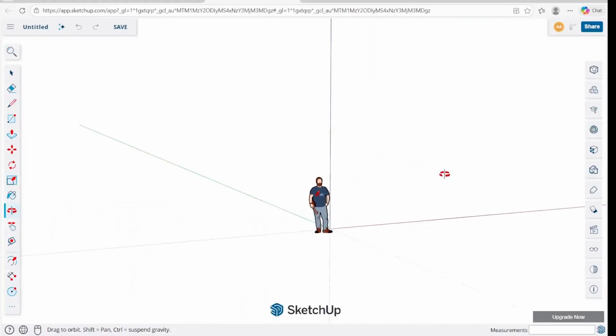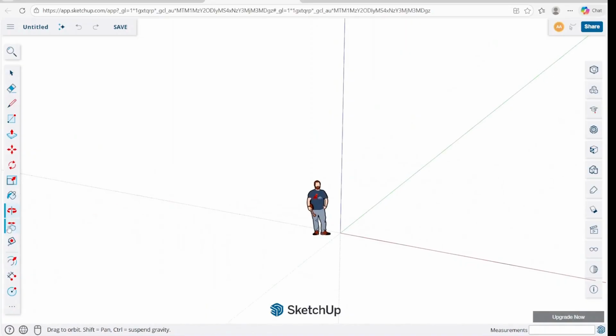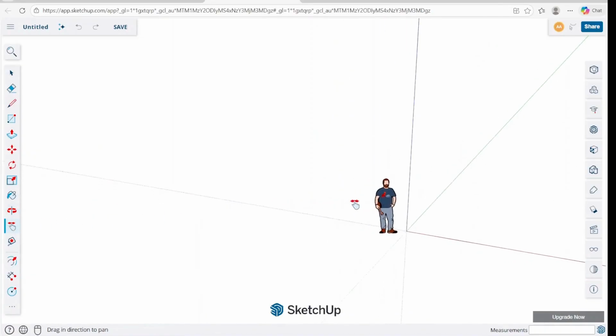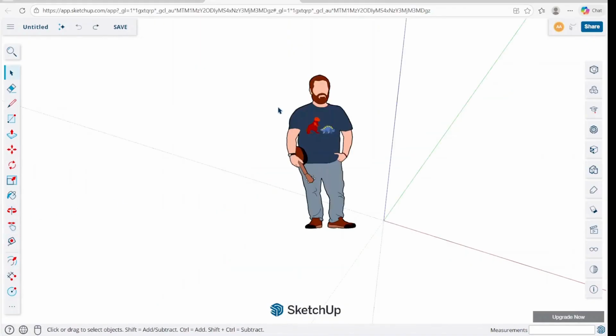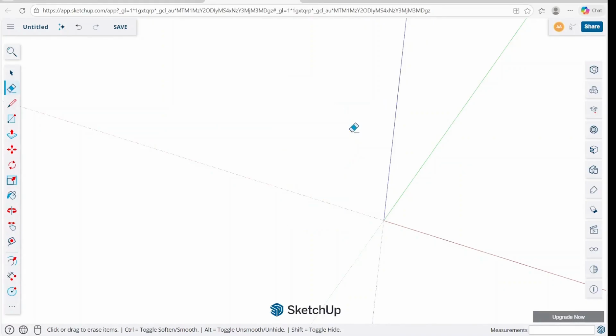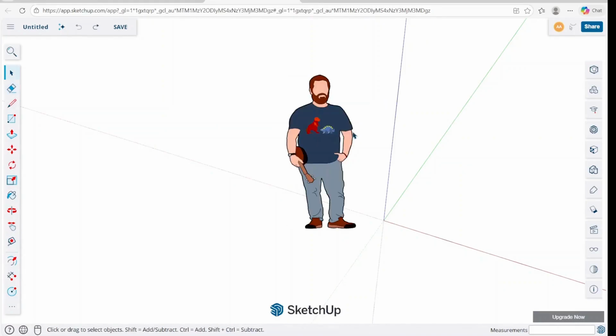You can use the icons for commands on the left side, or you can use your mouse for orbiting and panning to the objects. Aside from using the icon on the left or typing E for erase, you can also use delete button on your keyboard. For line command, you click in first point and end point each time. If you form a close shape, it will create a 2D solid surface.